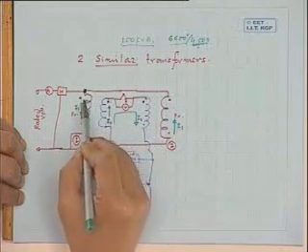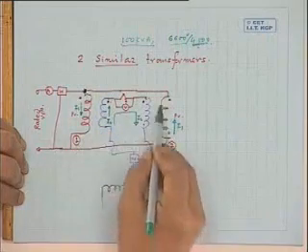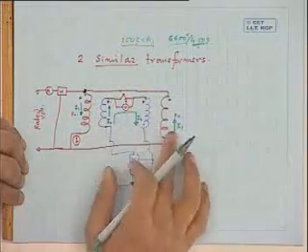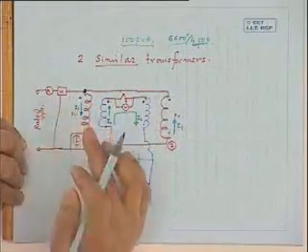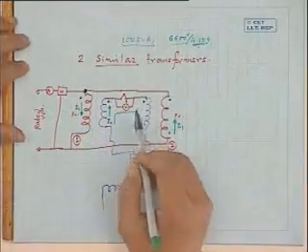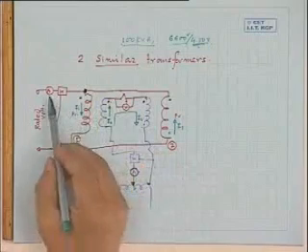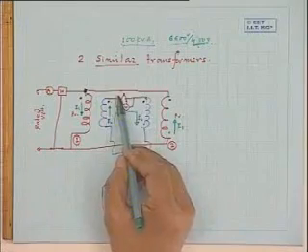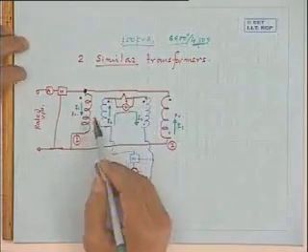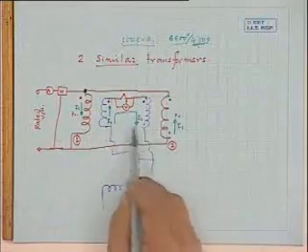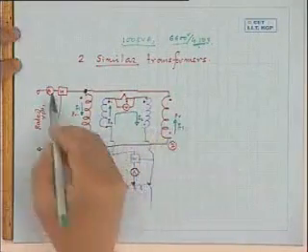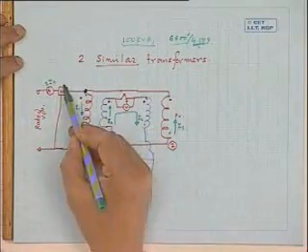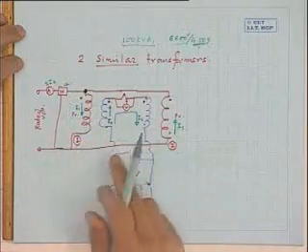Now obviously at these junctions, if you apply Kirchhoff's current law, this I1 will be circulating within these two windings. There will be no branch of this I1 to the supply side here. In fact, going back, when the switch was opened, how much will this ammeter be reading? When the switch was opened, you have not paralleled, it will not be zero, it will draw the sum of the no-load currents. This no-load current, this no-load current. This twice I0 it will draw from the supply.